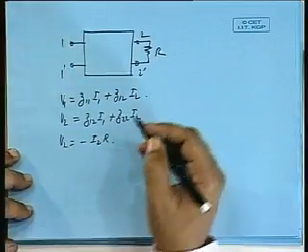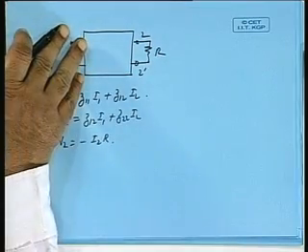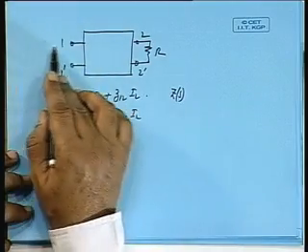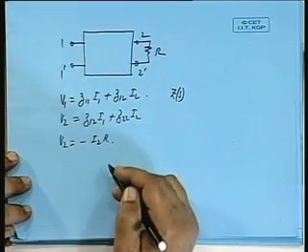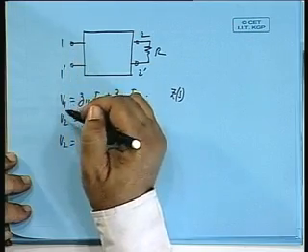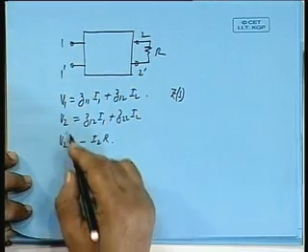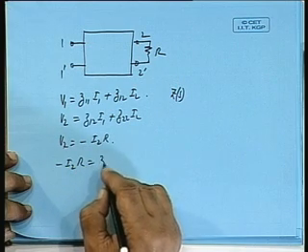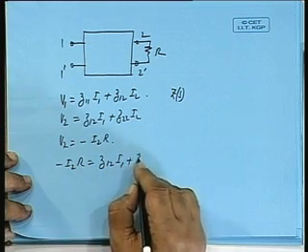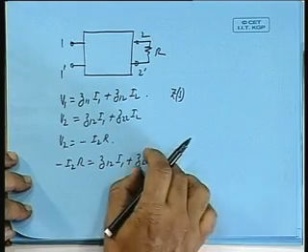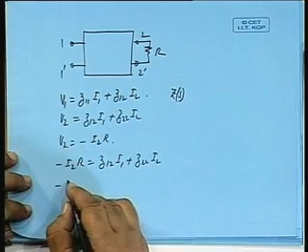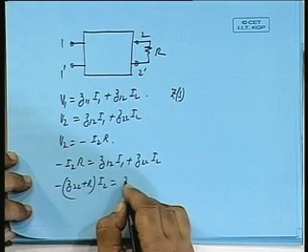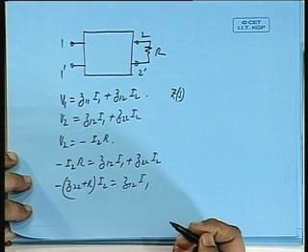Okay. So, what will be the impedance seen from this side 1 dashed? I call it ZS. Impedance seen from this side, that is V1 by I1 when this is terminated. So, let us substitute it here, minus I2 into R is equal to Z12 I1 plus Z22 I2. If I take I2 on this side, then minus (Z22 plus R) into I2 is Z12 I1.